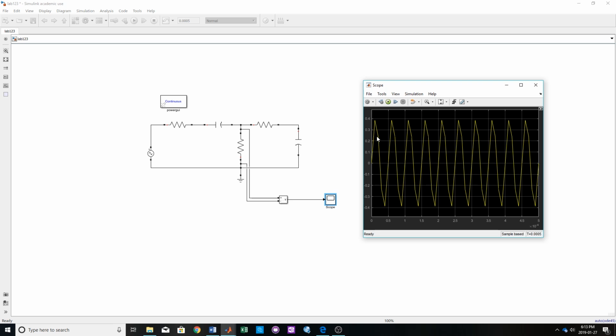So this is the voltage variation as time goes by, right? And this is basically 5 times 10 to the power of -4 seconds. Okay, that's the maximum. So that's what we put in here. So that's basically corresponding to how many seconds your x-axis is going to go till, right? So the limit on your x-axis, like the maximum that you can go. So this is like how long your simulation will run for. So if you want to just run for, like, let's say 2 periods, you'll do 1 times 10 to the power of -4, for example.